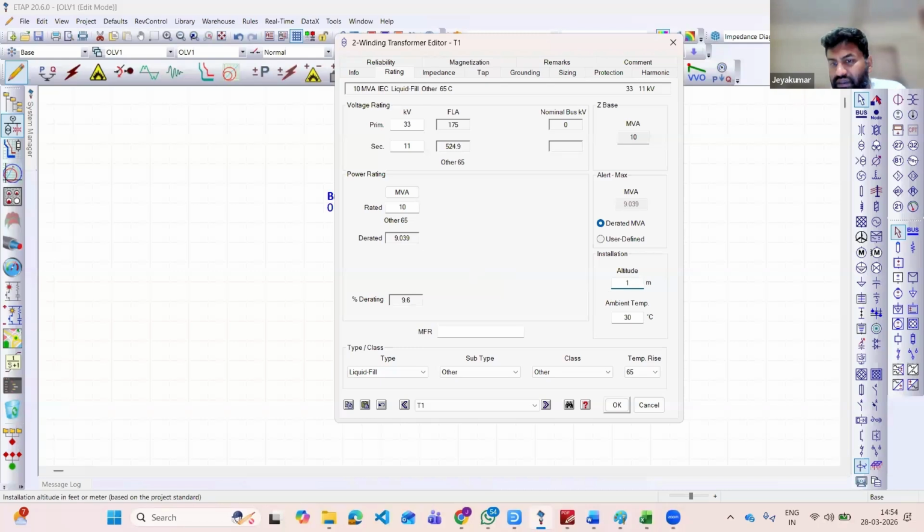Maybe from 1100 onwards, you see, right? Your transformer is derated by 2%. So even though you are buying a 10 MVA transformer, if you install it at 11,100 elevation, your actual transformer rating will be 9.8 only. It is like the cable derating we talked about, in the same manner it happens, right?